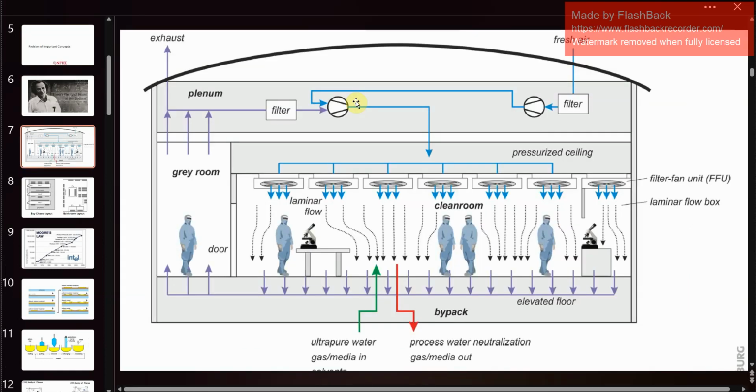And then we discussed what a clean room is. A clean room is a room which doesn't have any dust particles. The main thing is that the features you achieve in MEMS are in the micrometer range, which is equivalent to the size of dust particles. That is why dust particles have to be eliminated as much as possible. So this is how a typical clean room looks.